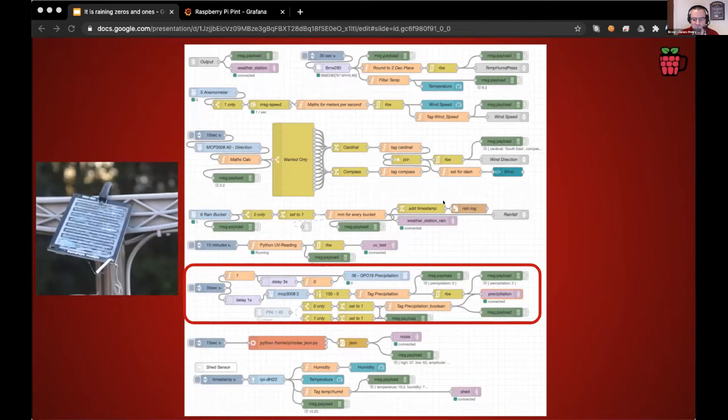And this actually came in really useful further on. So what we've got going on in here, and this was my workaround, as Paul discovered with the oxidizing and eroding of the contacts on these: every 30 seconds we turn pin 16 on. That's what's powering the reader for this.